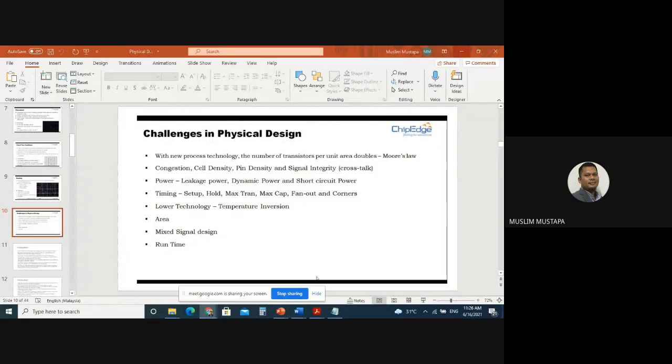So they used copper. Because there are a lot of copper lines, when they bundle them up, sometimes they put insulation so that they don't touch each other. But when they put it under the hole, sometimes a mouse bites the insulator and opens up the copper, and sometimes when it's raining, water fills up the cable line.